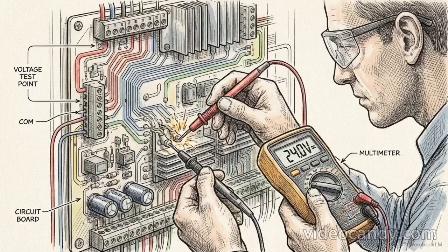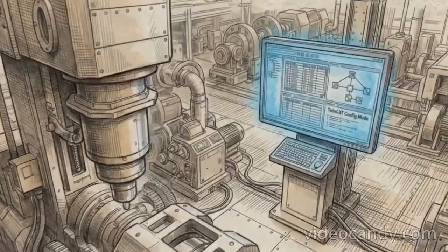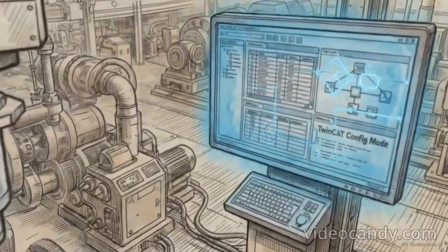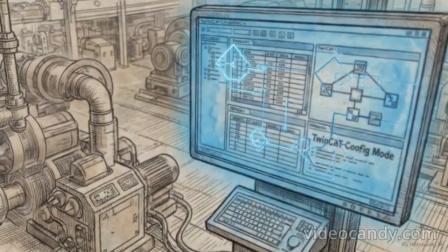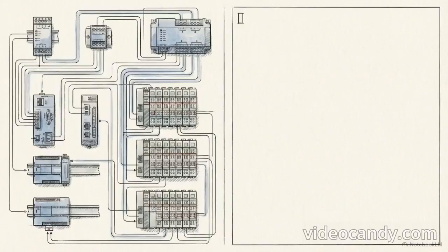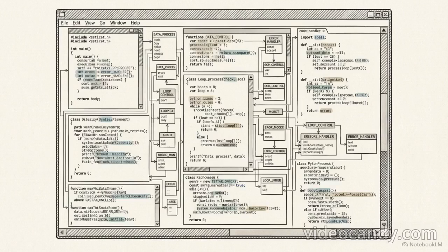Following the scan, the system prompts the user to enable free run mode. Enabling free run allows the programmer to directly manipulate terminal input and output values while still restricted to config mode. This serves as an essential diagnostic tool for purely physical hardware verification. The scanning phase translates dumb physical hardware on the factory floor into a structured, addressable digital database inside the TwinCAT environment.